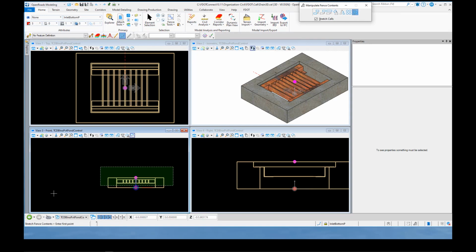Now in this case, this particular structure would need to be, let's say, 5 foot tall, just to be able to appropriately hold the weirs and have the orifice located at the position it needs to be. These are things that you're going to have to determine before you get to this point so that you'll know how far to stretch your cell. But I'm going to say 5 foot just so that we have plenty of room to work on placing the orifice and the weirs.